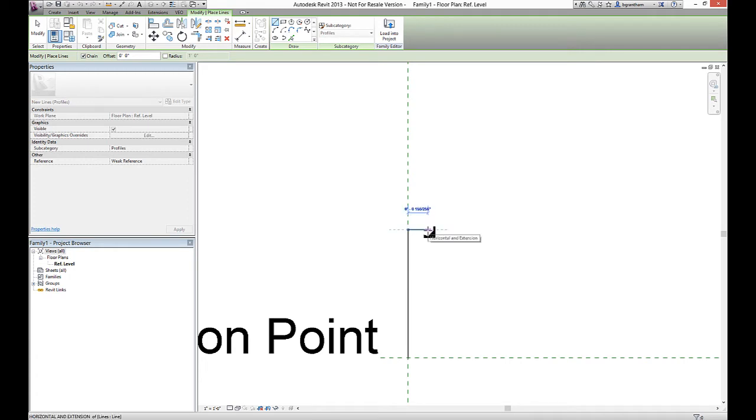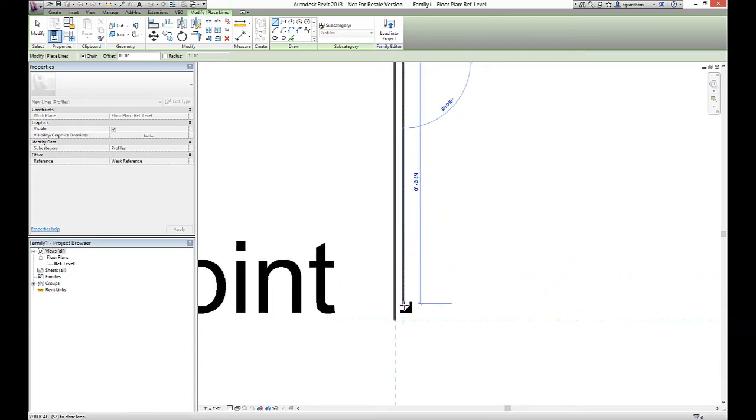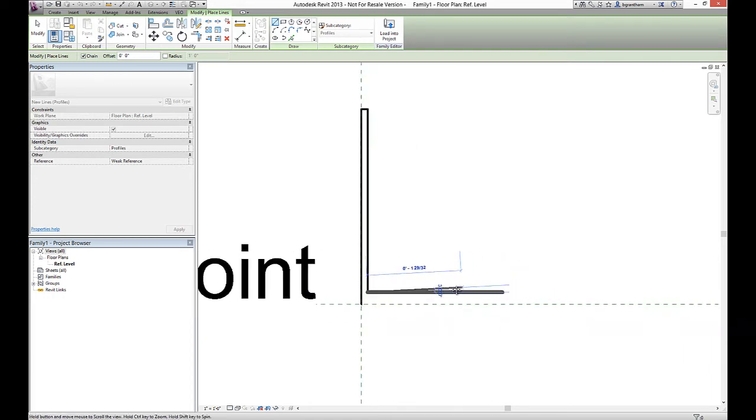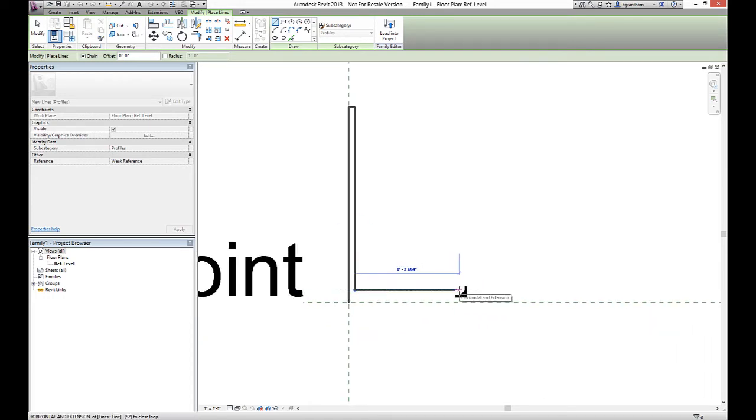It's going to be an 1/8 inch, 1/4 inch, 1/8 inch stump on top. Come down. Needs to be 3 7/8, 3 3/4 off. That gives us a 1/4 inch for the floor to be even. At this point, let's go ahead and make this 3 inches. And all profiles have to close, so you want to make sure this is almost like a continuous polyline.